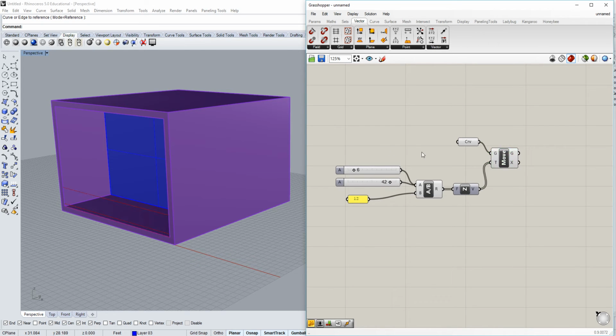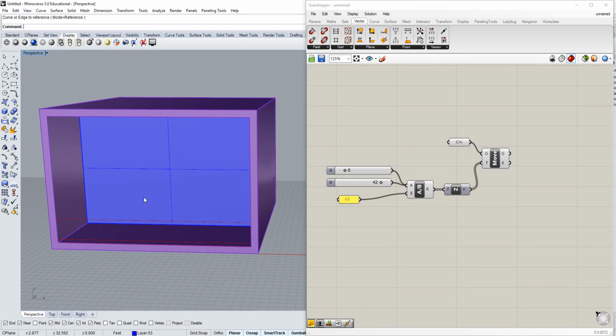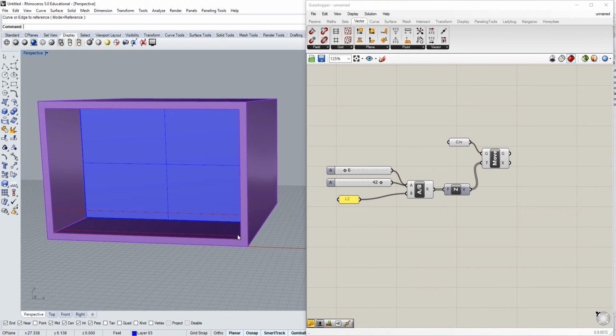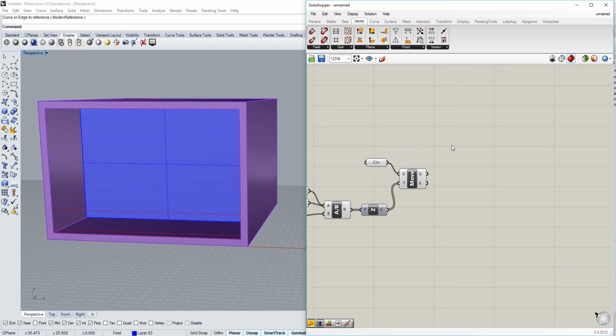So I've got one at 6 inches, I've got one at 42 inches, and I need to start progressing into actually developing the subdivisions for the panels, really. And there are a number of ways of doing this. In fact, what I am going to do is pull it off the edges slightly. And so I'm going to reparametrize only in one direction the edge of this rail so that it doesn't hit the side. So I'll have to make a surface first, then reparametrize it.